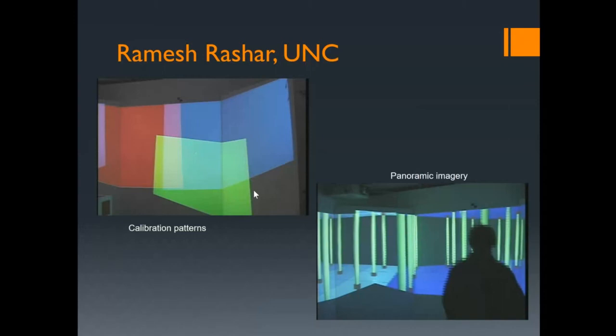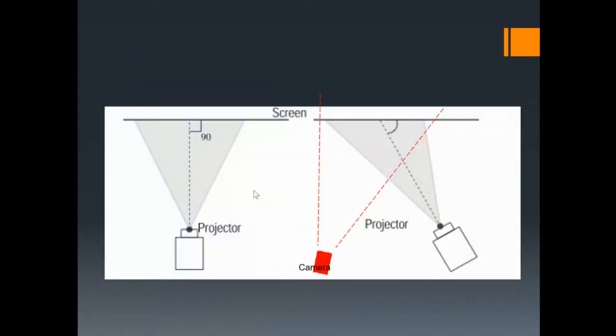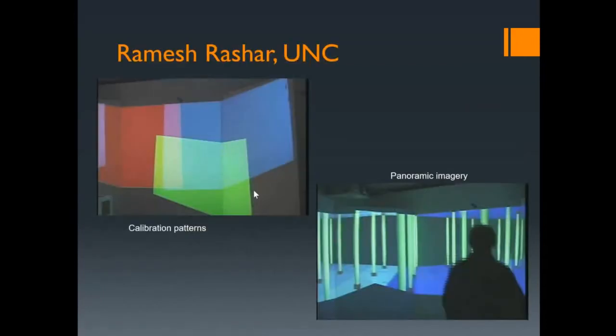So you can see here with the camera, just like what we said before, with the camera like that, you can capture this distortion and the overlapping areas. Okay, then you can actually recalculate that, and that's what it's doing for the whole thing here. It recalculates what angle that projector has related to the physical space. Once you have that, you correct for it, creating a correction factor for all these projectors to correct the image before they project it out into the space.